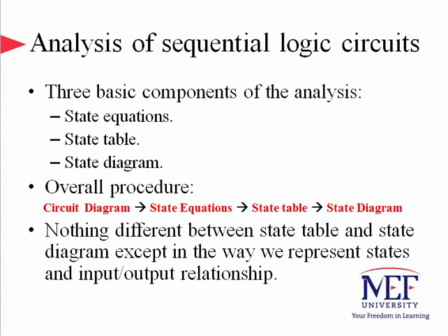The behavior of a clocked sequential circuit is derived from the inputs, outputs, and the present state of the flip-flops. The analysis of a sequential circuit is all about determining the time sequence of inputs, outputs, and the internal states. One of the important tools for the analysis is the state equations. A state equation specifies the next state as a function of the present state and the inputs.